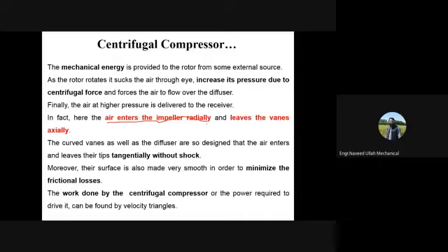We will be having absolute velocities, relative velocities, blade velocities, the same angles: alpha 1, alpha 2, right, and beta 1, beta 2, etc. So most of the things are the same, but here, if you see, over there in the impulse turbine the nozzle was inclined at a certain angle. So that was actually the angle of incidence over there, alpha 1, or alpha I, you can say the inlet angle.